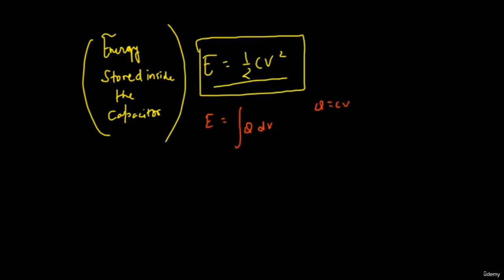So in the next line we are going to write C V dV, and in place of that, C is the constant, we take it outside, V dV, and on integrating we are going to get simply C V square divided by 2, that we are writing as half C V square. Well, if you don't know much about the integration or are not interested in this one, you can just work with this one. This is okay either.